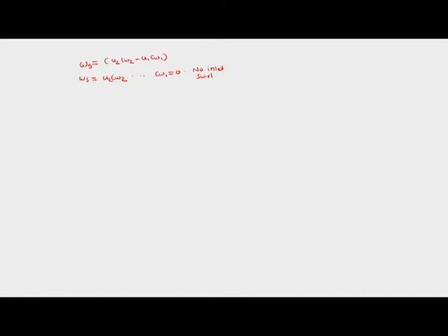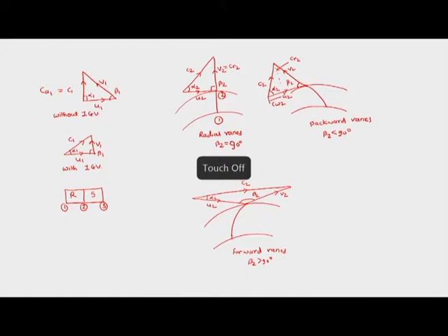So in the case of no inlet swirl, we will have swirl velocity or whirling velocity at the inlet as 0. But here we would have some outlet swirl velocity, U2 CW2. Practically speaking, if we go back and look at the radial case, then U2 is actually equal to CW2 in the radial case. Okay, so having known U2 is equal to CW2, we can write W stage for the centrifugal compressor is equal to U2 square. This is for the ideal case.